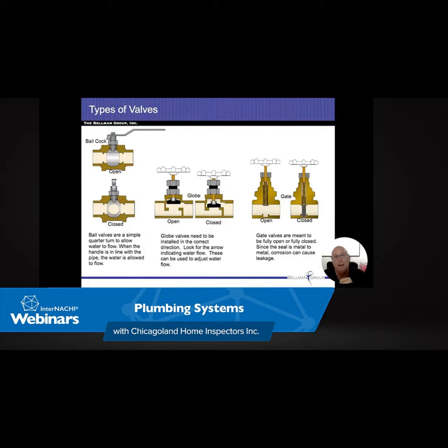Now, the biggest clue, if it's galvanized, and it would look kind of like lead as well, galvanized is not soft temper. And anytime I use the word soft temper, I'm talking about something being flexible. If it's hard and stiff and not really bendable or flexible, that's hard temper. So copper comes in both hard temper and soft temper. Some things, if we bend them, they'll kink. Other ones, like gas lines, come in a coil, and we can straighten those out.